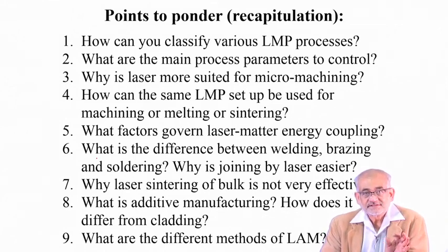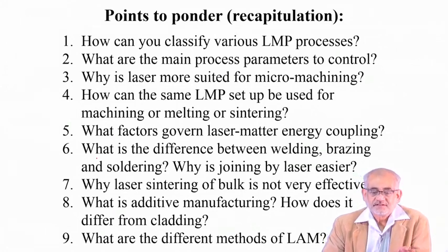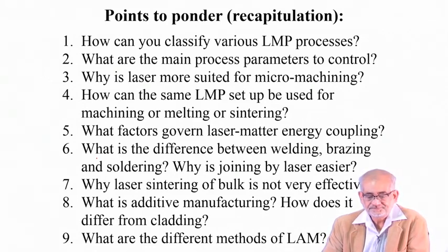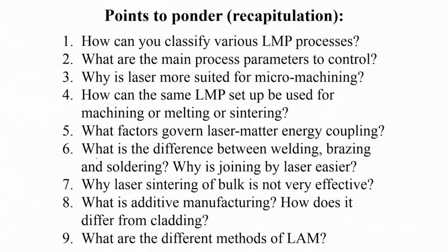So using the same laser, by changing the parameters, the power density and the interaction time, you can do either only heating, you can do sintering for that matter, you can do melting, solidification, you can even do machining with or without a carrier gas like oxygen. The surface condition is very important in terms of the efficiency of coupling the laser and matter, and also the wavelength, and the various material properties like the density, the melting temperature, the specific heat, and so on and so forth are also very important.